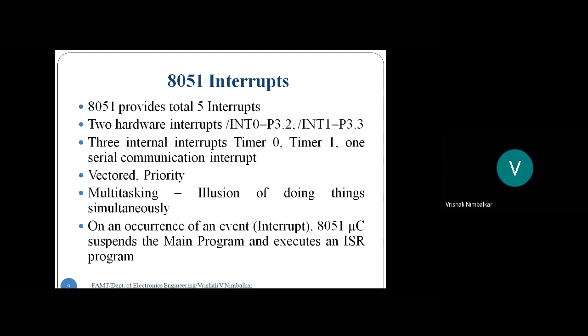Vectored means one fixed address is automatically loaded in the program counter and the microcontroller jumps automatically. Non-vectored means that with the help of instructions, we load the program counter, and then the microcontroller jumps to the vector address.